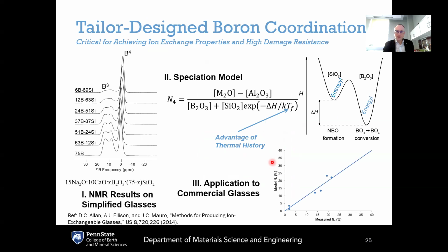Now, in some of the newer Gorilla Glasses, starting with Gorilla Glass 3, another feature that had been introduced to help improve the mechanical performance is intrinsic damage resistance, which was trademarked as native damage resistance. And this is actually including boron in a threefold coordination state in the glass. As you know from Chapter 5, boron can exist in either trigonal configuration, B3, or tetrahedral configuration, B4. If it is included in the glass in trigonal configuration, that creates a more open structure without getting in the way of ion exchange and also allowing for the ability of the glass to compress.